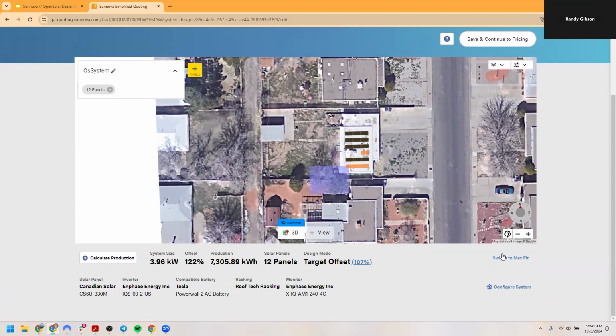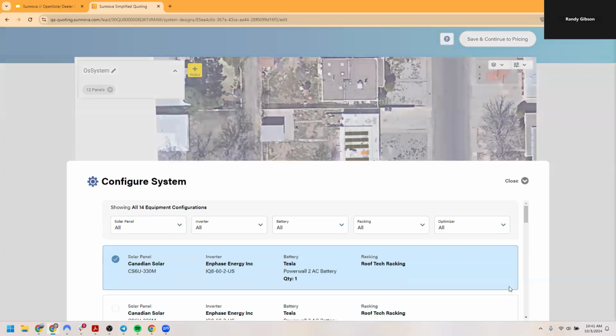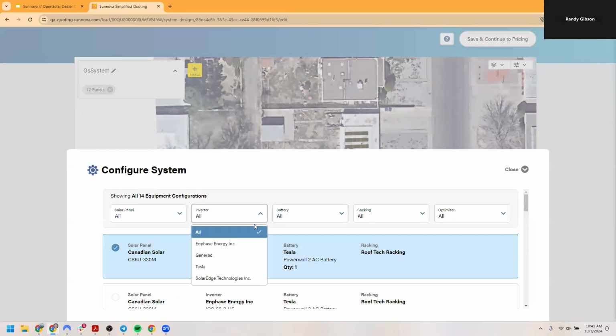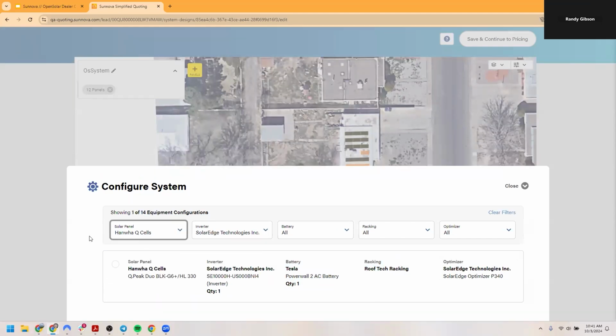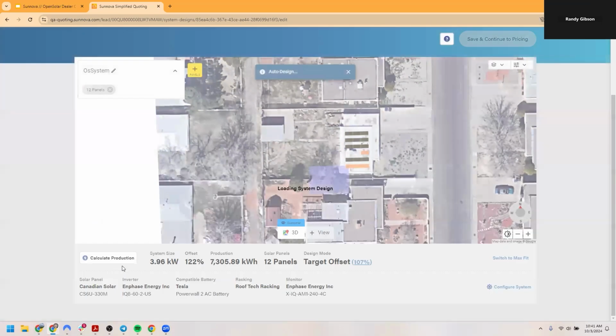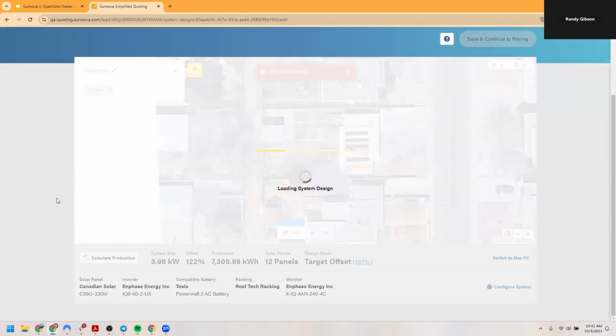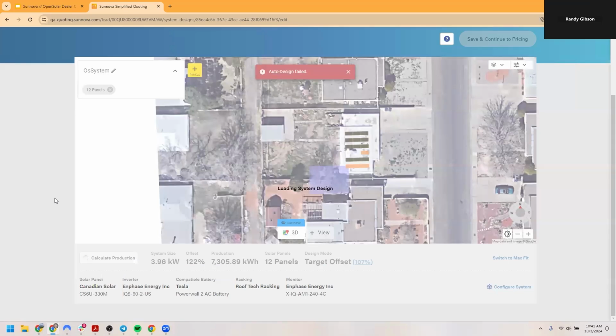And if so, just make sure you have the correct size inverter selected. You might be selecting an inverter that's too small, and then that will not allow you to get the design that you're targeting, especially if you got like a 3800 or something like that, or just see if you can select a larger inverter in your equipment packages under the configuration system, configure system.